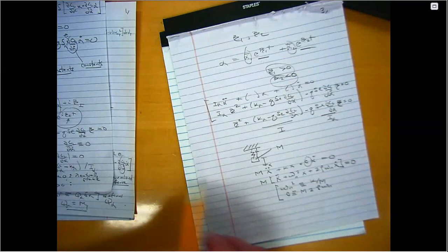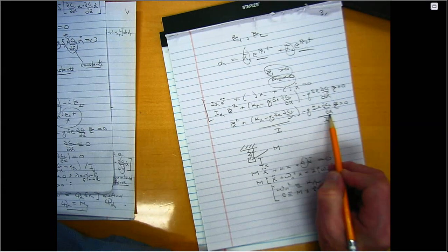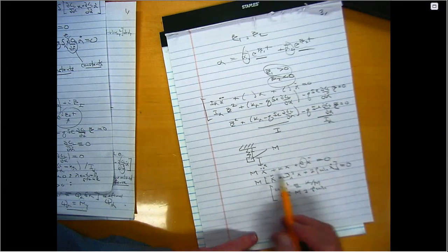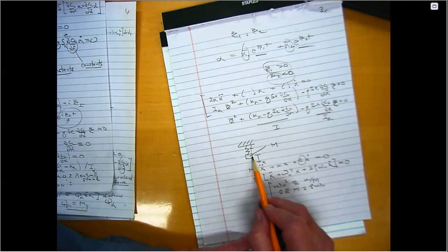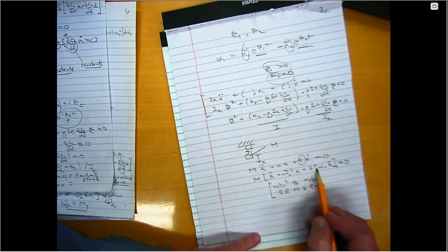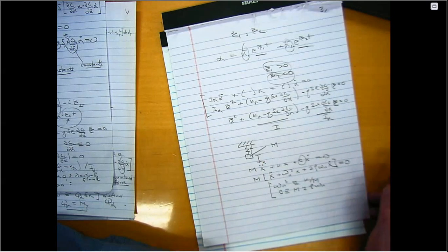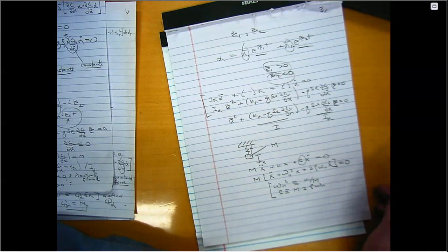So the point I want to make is this term is damping. This is a damping term. And you probably realize that the solution is normally damped for this case, when C is a positive number. If C ever becomes negative, I have a dashpot with negative damping. And in the aerodynamic flow of a ring, the damping can indeed become negative.